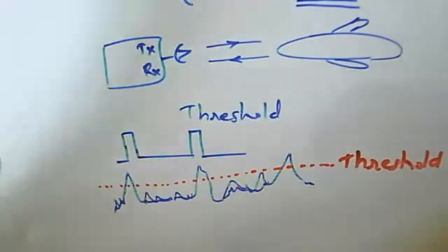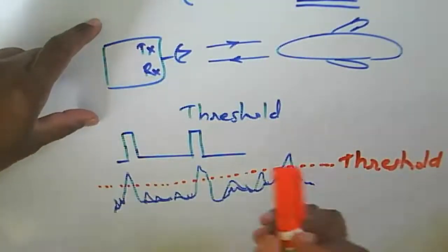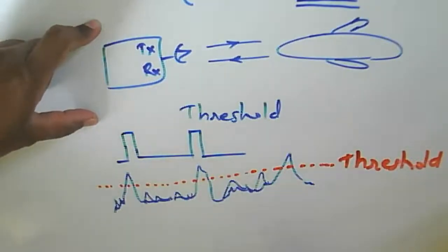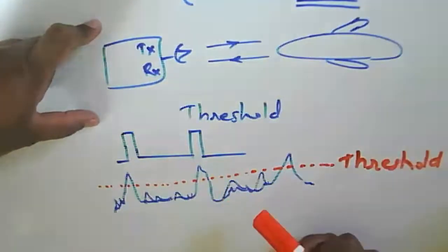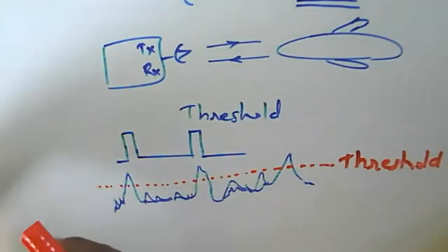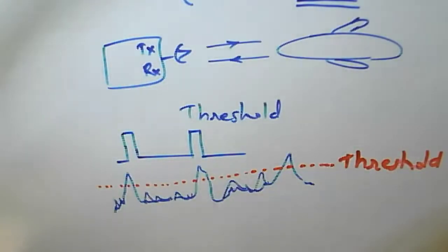There is no object, or spurious or any jamming signal reaches the radar, but it is not indicating that an object is there. But we are getting some signal that is more than that threshold value, so that is nothing but a false alarm for the radar, a false pulse detected by the radar. So that's why we need to know what is the probability of a false alarm detected by the radar there.